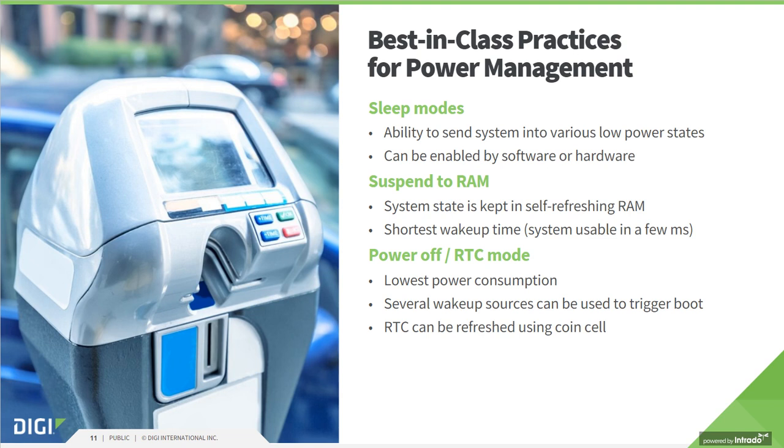If wake-up time is not the most relevant aspect in your application, you may want to opt for lowest power consumption instead. However, in most applications, simply cutting power is not sufficient. Often you want to maintain at least a clock to keep date and time, or offer more options to restart the system other than just attaching power. Many systems offer a power off or RTC mode to provide this functionality with as low as possible power consumption.